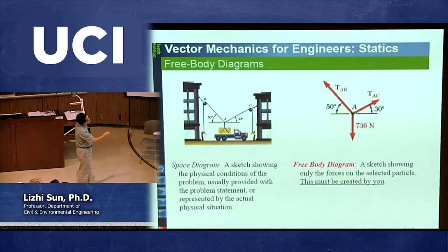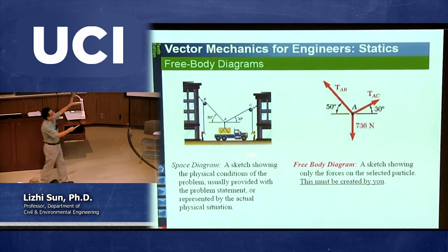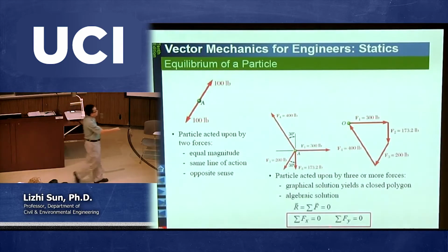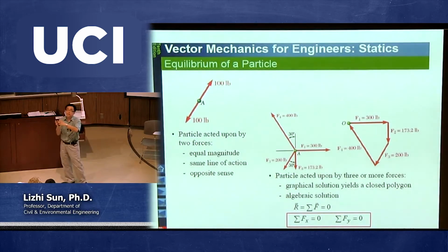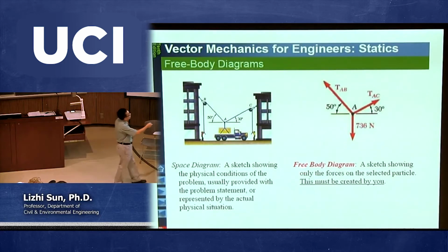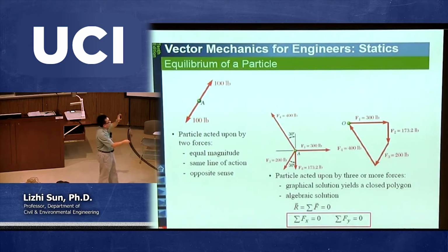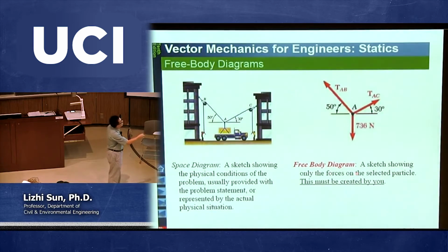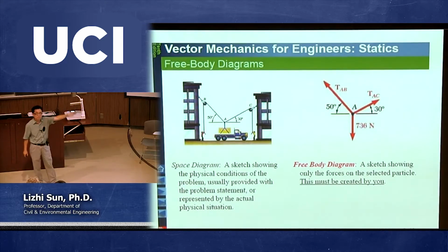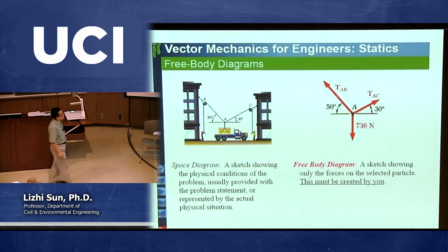Originally, you have forces acting somewhere in physical space. But in order for us to use these two equations, there is a bridge, a medium we need to use, and that is called the free body diagram. In fact, those equations are applied in the free body diagram. It's not from the original picture, although many people just go ahead and use the original picture. Many times you can do a good job, but the problem becomes too complicated. You better use the free body diagram. That's why I want to introduce the free body diagram.